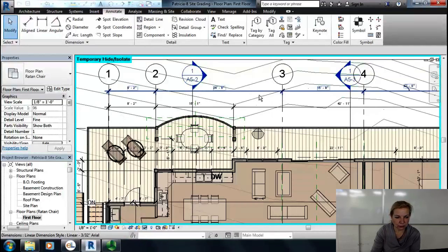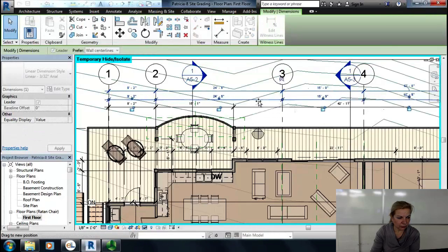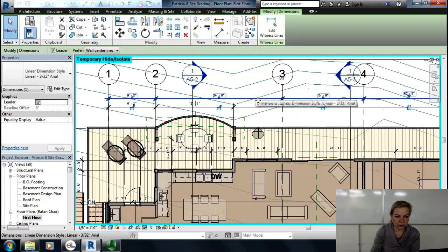I have grid, which you don't. And that's something I don't want to forget talking about: you also want your strings to look good and line up. From drafting classes, you should know by now that dimensions are about 10 to 12 millimeters apart, and about 10 millimeters when printed from the last object line. So when you're showing the outside scenario, like I'm showing decks and my furniture and the supported structure, it is up for questions whether that 10 millimeters should be from my wall, which is what I decided to do, or the last object, which is my deck.